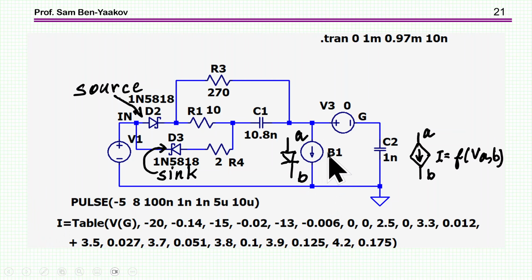So this emulates the diode, and the driver itself includes a square wave excitation. And then rather than having two outputs, I've put two diodes, one for sourcing and one for sinking. And here is the network of this driver.